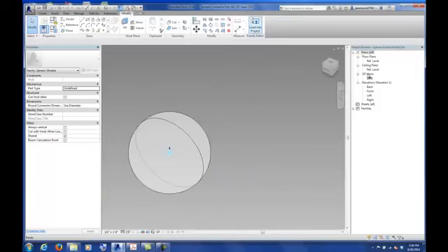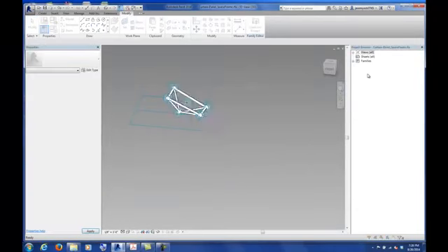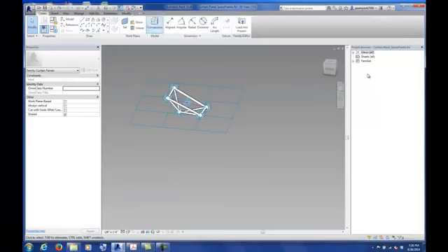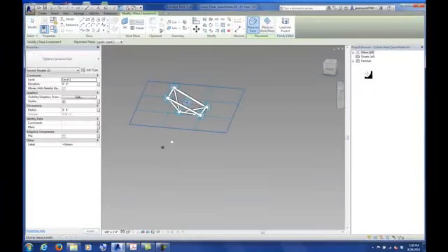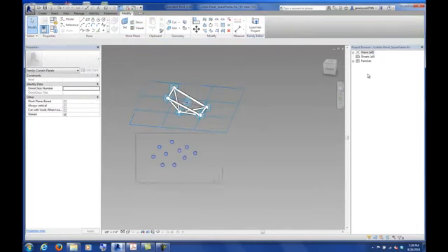Now if I load that back into my project and override it, hit create component to place it. Now wherever I click, my sphere should be there. So those of you that were having that issue, all of you had the same common thing: it wasn't an adaptive component, so that should fix it.